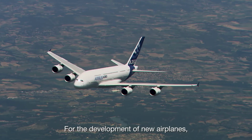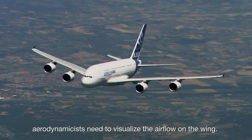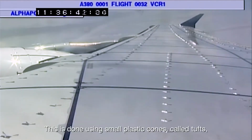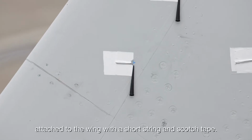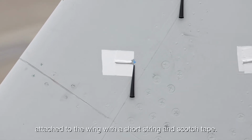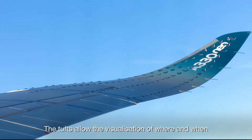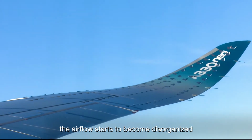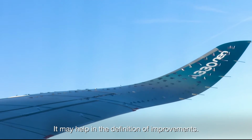For the development of new airplanes, aerodynamicists need to visualize the airflow on the wing. This is done using small plastic cones, called tufts, attached to the wing with a short string and Scotch tape. The tufts allow the visualization of where and when the airflow starts to become disorganized when approaching the stall. It may help in the definition of improvements.